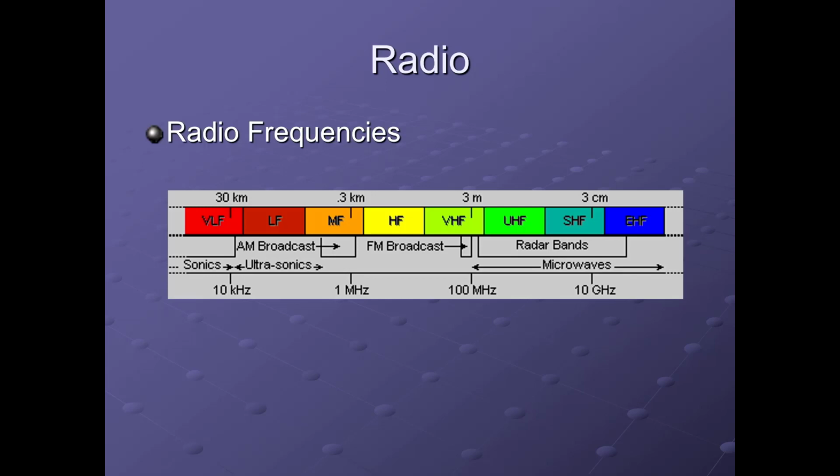There are certain characteristics that you would leverage for, say, VHF over UHF. There's certainly a huge difference in the wavelength of a very low frequency to a very high frequency. Look at that, 30 kilometers and 3 meters, huge difference. And it's things like that that change the size of anything like a resonator or a duplexer or an antenna. Back in the old days, as an example, cell phones came out at 800 megahertz, and at 800 megahertz you had a much bigger cell phone, a much bigger antenna, and things like that.